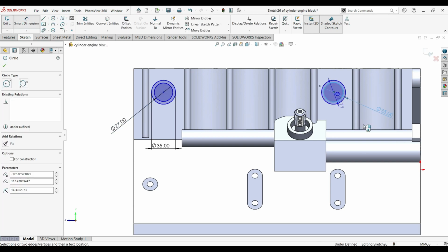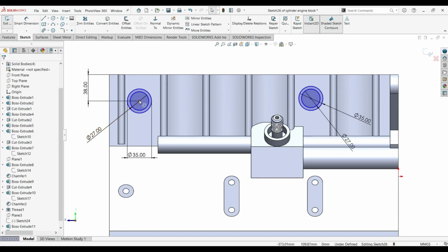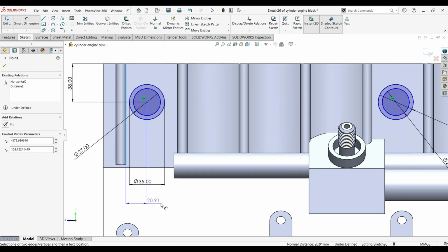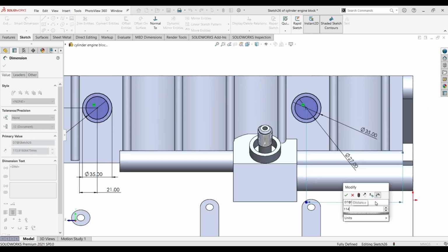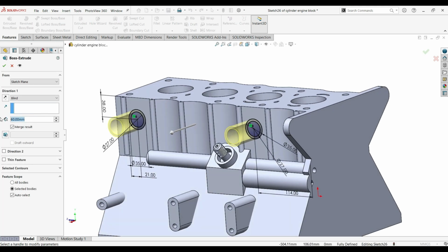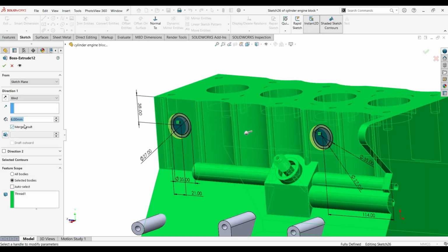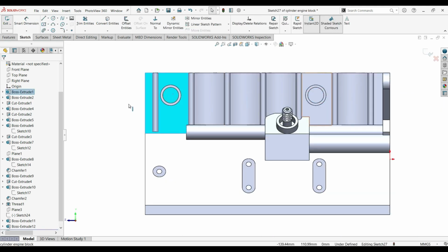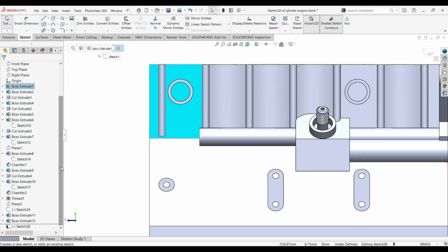One thing here: when you extrude, make sure that they're not matched. You don't want to match with the main drawing, so just extrude without match, because we'll need to mirror. Just go to the extrude, and we'll put 6 here, and very important, don't merge. We don't want to merge both of them.